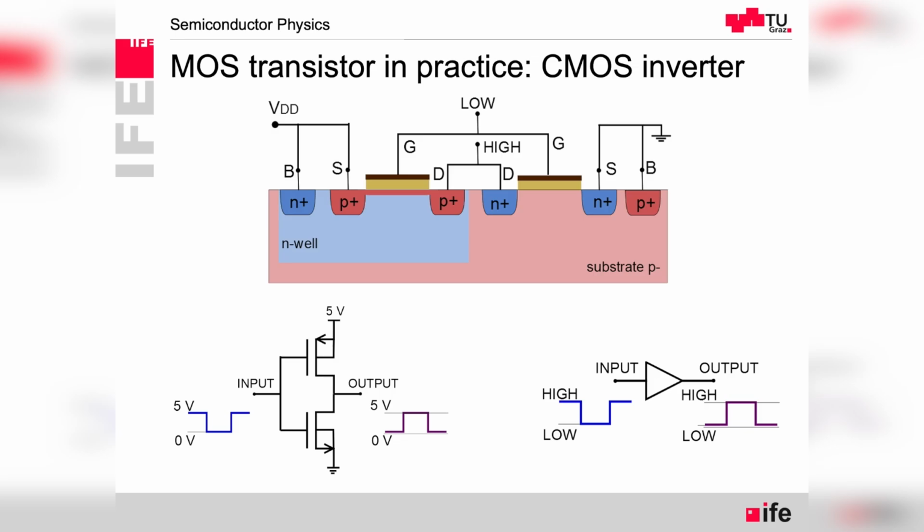The pattern and the duration is very much dependent on what we are talking about. For DRAM, we need to have regular refresh to reprogram the voltage. In this case, the example is for sample and hold, where we have not just a digital value like for DRAM, 0 or high, that is being stored, but we have something more complicated. There is an input voltage that we want to sample, and during the hold time, maybe there is another gate on the other side of the capacitor that goes to the digital to analog converter to read the voltage.